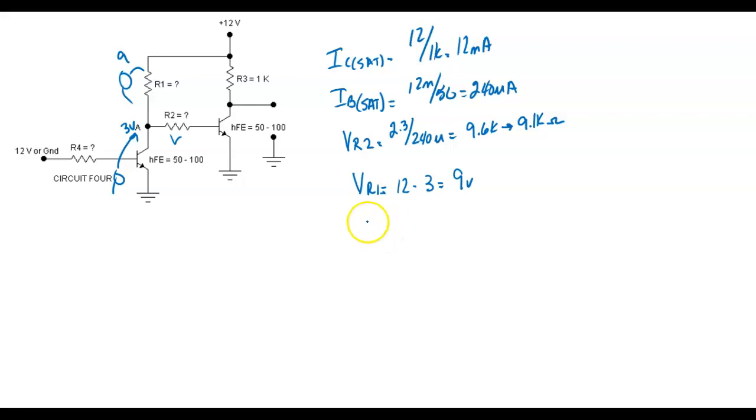Now we can calculate R1, and this is going to be approximately, guys. So what would R1 be? Yeah, but actually it wouldn't be 240, and that's why. It'd be a little more to get extremely accurate, but we're going to round anyway, because that 240 was what we'd get if we used a 9.6K, but we didn't use the 9.6K, we used a 9.1.